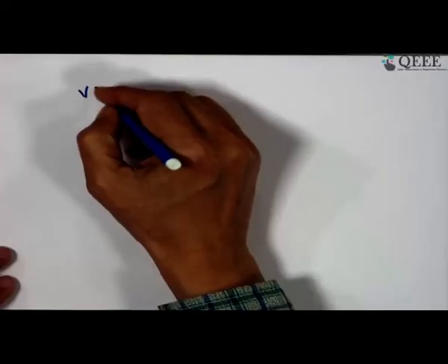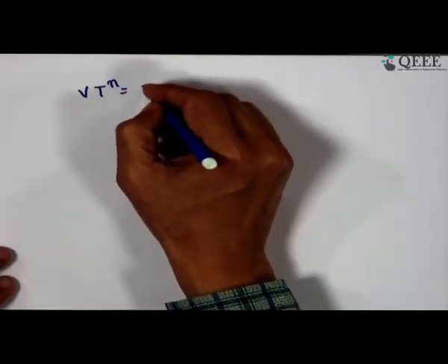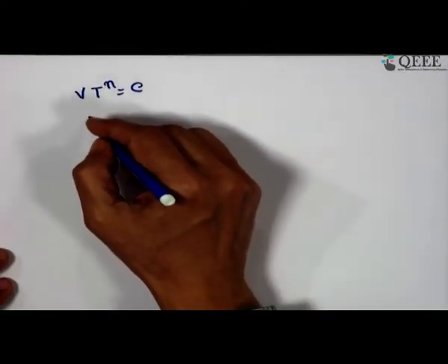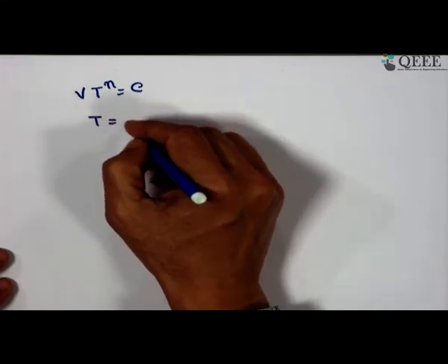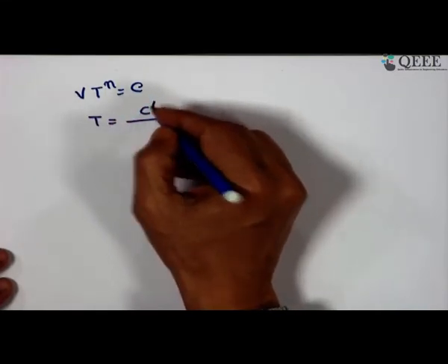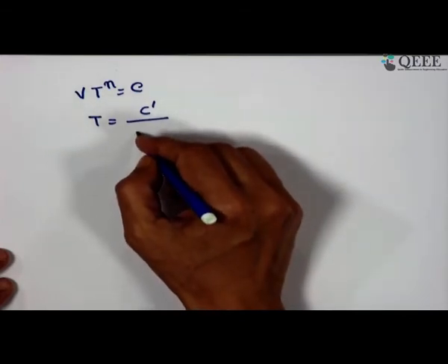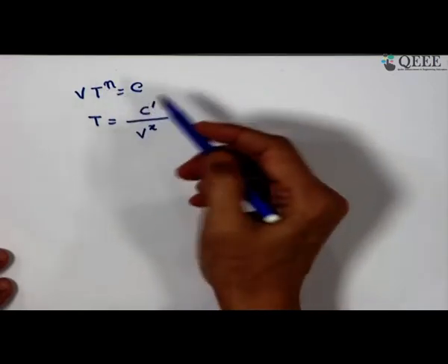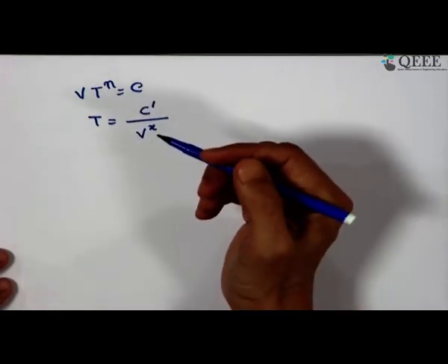We have mentioned this tool life and its dependence directly on velocity, that is Taylor's tool life equation, what we have seen as V T to the power n is equal to constant, but it can be more generalized in this form that T is equal to some constant, obviously this value will change, and then we can put it in the form of V to the power x. That means it is 1 upon n, it comes automatically.